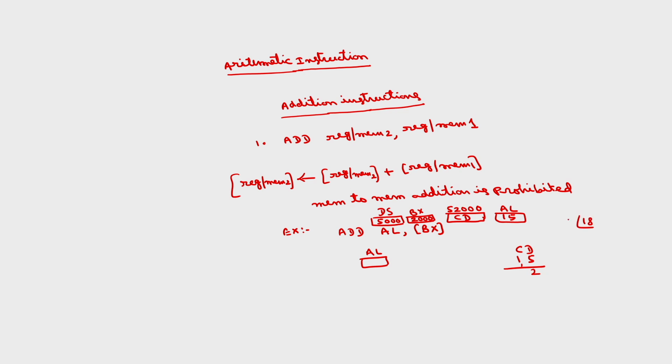If you convert 18 into hexadecimal, 18 divided by 16, 2 is the remainder, and 1 is the quotient. So 12 is the hexadecimal of 18. So in decimal this D is 13 plus 5 is 18, in hexadecimal it is 12. So C after that D, E, so this is E2. The carry flag will be reset. This particular addition instruction affects all the flags.